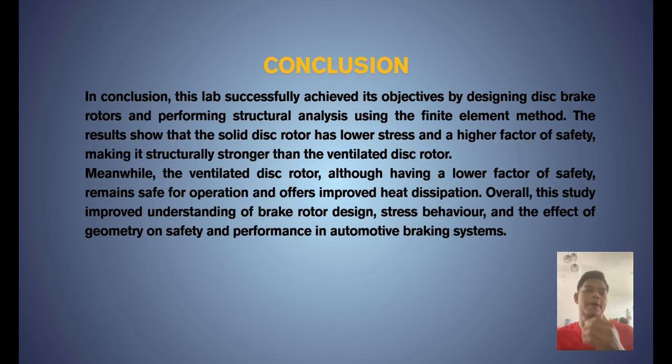Lastly, for the conclusion, this lab successfully achieved its objective by designing these brake rotors and performing structural analysis using the finite element method. The results show that the solid disc rotor has lower stress and higher factor of safety, making it structurally stronger than the ventilated disc rotor. Meanwhile, the ventilated disc rotor, although having a lower factor of safety, remains safe for operation and offers improved heat dissipation. Overall, this study improved understanding of brake rotor design, stress behavior, and the effect of geometry on safety and performance in automotive braking systems.